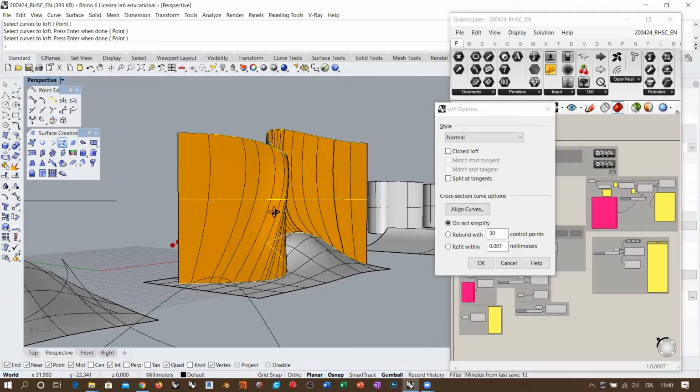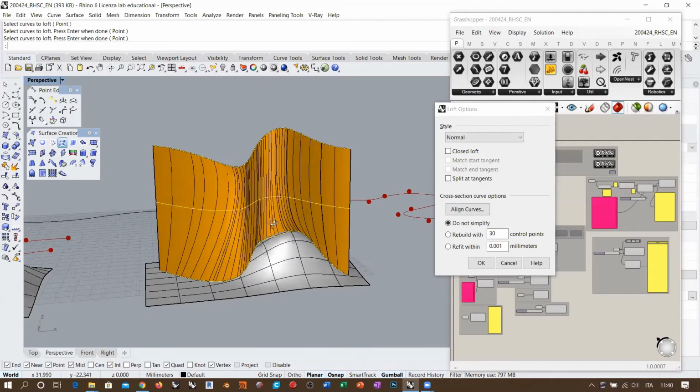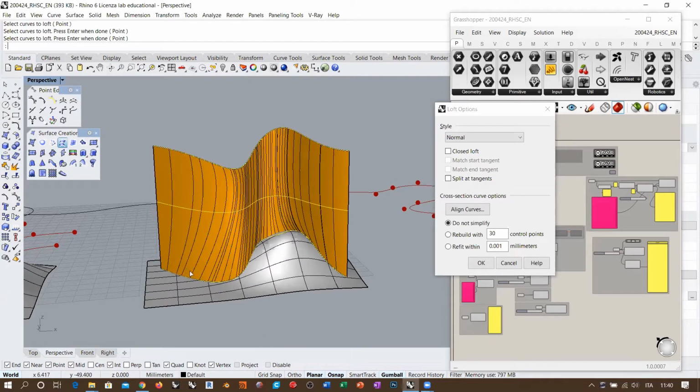What happens is this. Now, this is extremely problematic because the isocurves depend so much on the fact that the lower curve has a very high level of complexity. So remember that isocurves are not lines. What we are seeing here is the presence of an extremely high amount of spans, and also uneven subdivisions of the curve in terms of spans and knots.